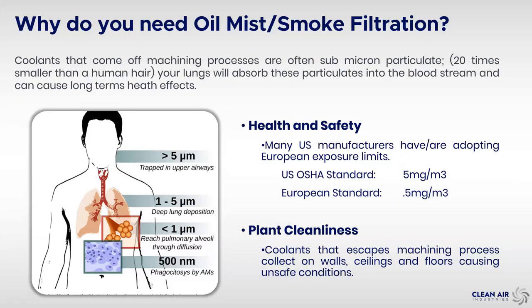But anyway, just to start off, I wanted to talk to you guys about the oil mist and oil smoke filtration and where it comes from, and that is mostly machining processes. These new high spindle speed machines now, they can really produce some very small air particulate that is very harmful to your lungs. So you can see in the diagram over there, these oil mists, they'll actually create